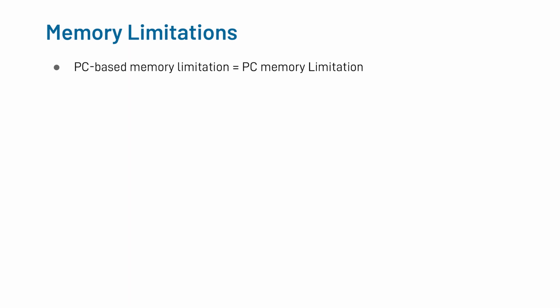On the other hand, for drive-based controllers, the storage limitation is roughly 5 gigabytes. This is just due to the nature of standalone drives and the memory capabilities currently available. Again, this is because the ISMC controller lives on the drive itself, and so all the memory is stored there as well. Now, this is just the memory available offline for a drive-based controller. While connected to a computer, they are still able to access files located on the computer itself. So if you stored your AeroScript programs or MCD files on the desktop, you can still open and run those from the desktop. Just the onboard user file system has this roughly 5 gigabyte storage limitation.